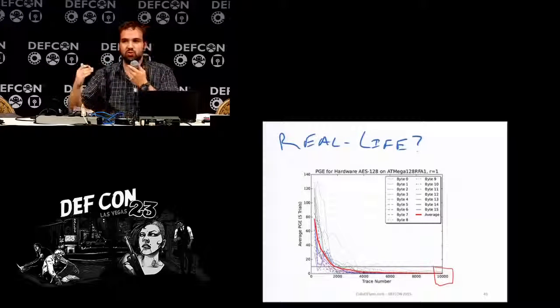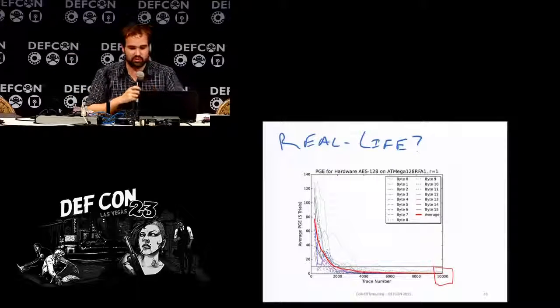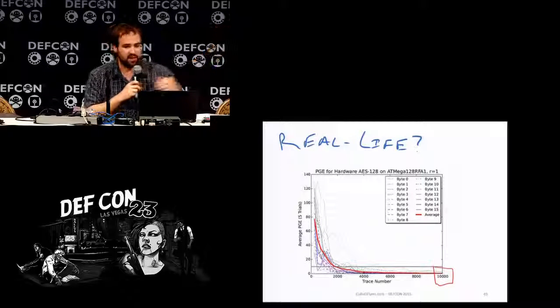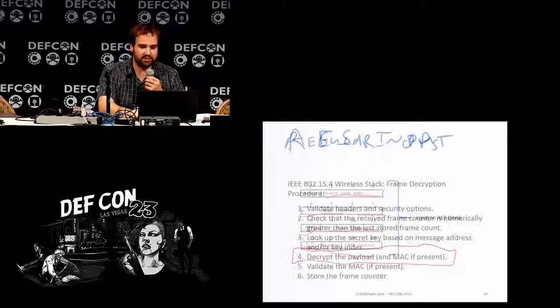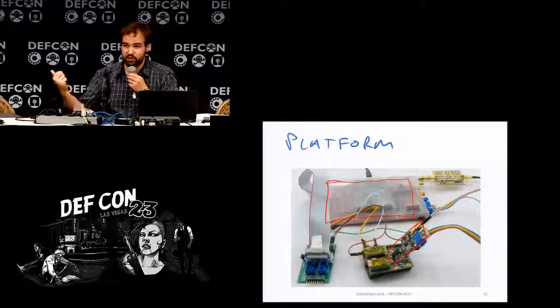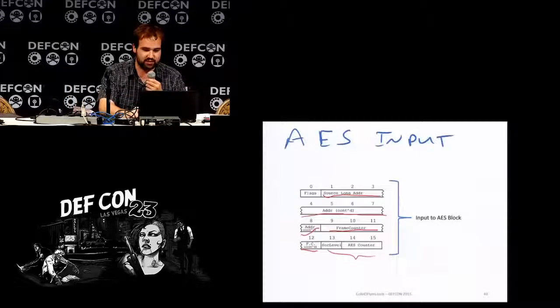If the entropy is 2, I needed to do 2 wrong byte guesses. It's a fairly straightforward metric, and you can really see that after about 10,000 traces, I was able to recover the key. And again, this is a real 802.15.4 stack on a real device on a real dev board. There are no tricks to make it easier here.